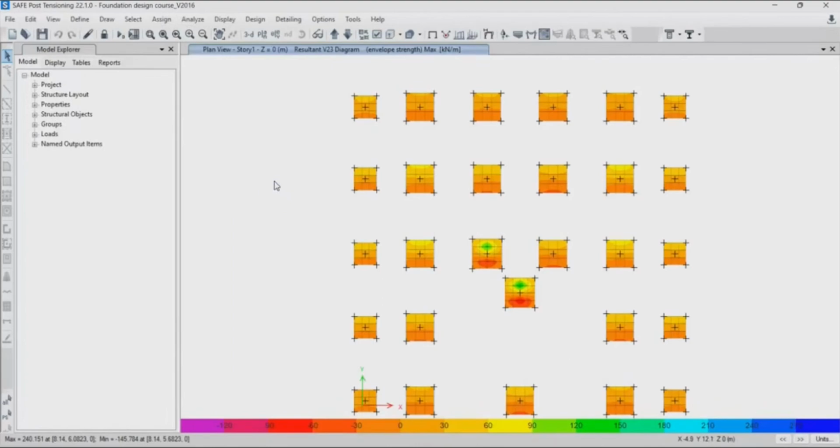Now we are going to move to the design of the isolated footing. So there are two methods we use for designing the isolated footing. We can either go with the strip-based method, or we can go with the finite element-based method. Okay, so let's try to understand this method. For the strip-based method, what this basically does is force the finite element software to behave like a traditional structural engineer doing the hand calculation. Okay, so it looks at your footing as a series of imaginary concrete beams.